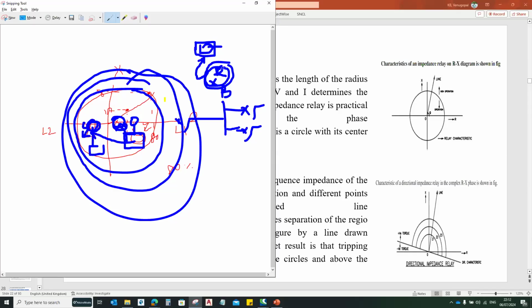Yes. Actually, the resistance and reactance values are provided by ourselves, right? Yes, we are giving the conductor resistance value and the reactance value. That's the reason, whenever you are doing relay setting calculations, the relay setting engineer will ask for the inputs of R values and X values.